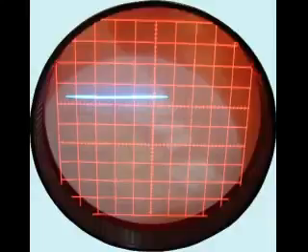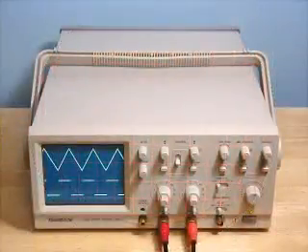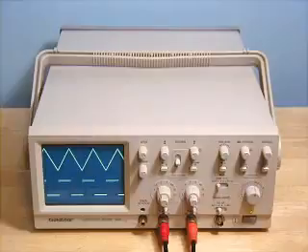The greater the voltage between the deflection plates, the more the electron beam will be bent from its straight path, and the further the glowing spot will be seen from the center of the end of the tube. This principle is used in the oscilloscope for measuring changing voltages. An oscilloscope is able to draw a graph of a changing voltage. It can show a graph of a voltage or signal that changes far too fast for a meter to register.